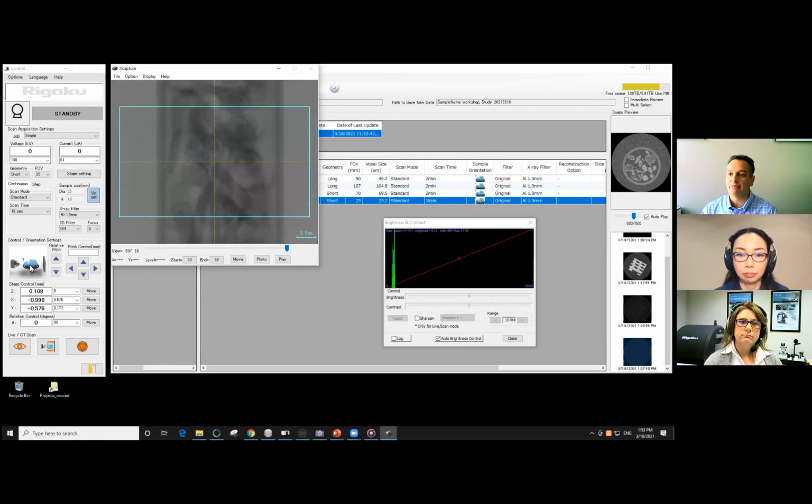So looking at identification and diagnosis of that type of damage, I think, if I'm asking that correctly. Yep. Right, looking at damage and cracks, CT is great for that. How you image it and the resolution at which you image it will be impacted by the feature size of that damage. So if it's really small, then you need a small field of view.